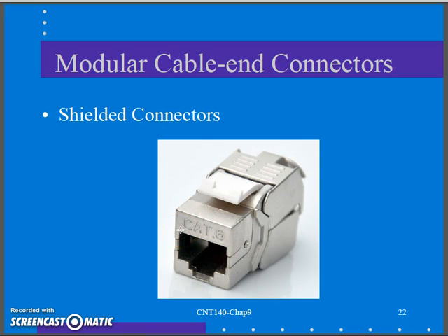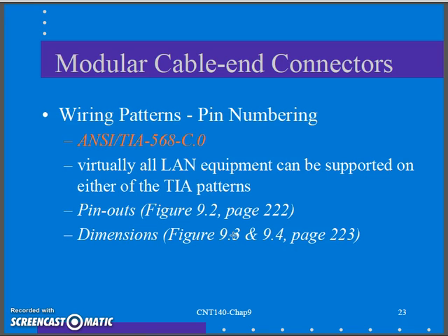So as I plug in my cable, the shielding on my cable is picking up the noise and makes contact with the connector. As I plug into here, it's making contact here, and all of that is getting attached to ground, and all the noise is being sent away.